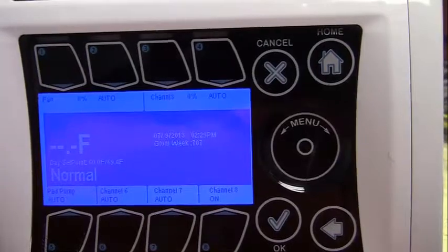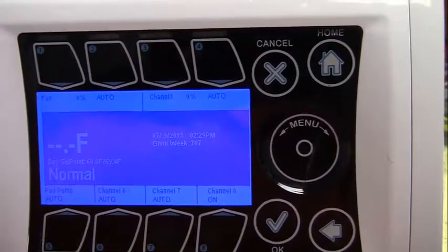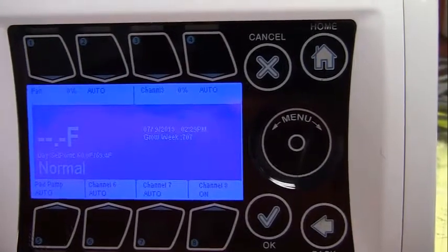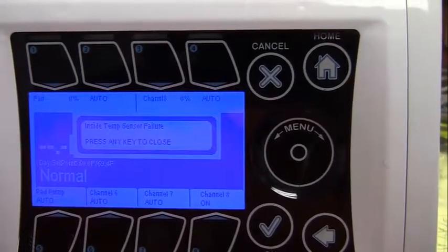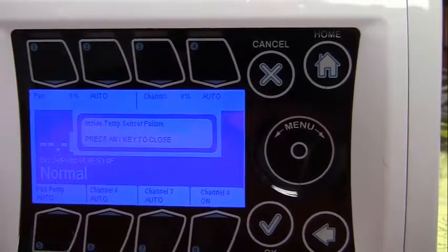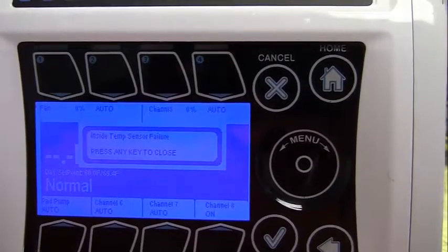Assigning of stages can be done for a given channel through the Assign Stage button at the equipment settings, or directly through the staging line on the main menu. The stage settings can be set for temperature stages and humidity stages. Note there are 8 temperature stages and 4 humidity stages.